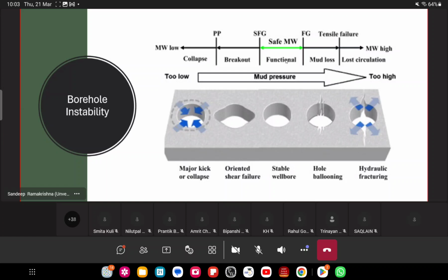Fractures are in the maximum stress direction. And if it is too low, obviously, you're below the pore pressure, then you cannot sustain this wellbore. You're going to end up collapsing. You're going to see shear failures, like how you see tensile failure here. It should have been labeled shear failure on this side, or,